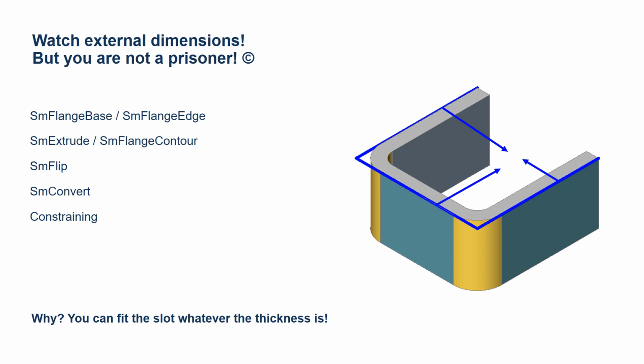And next, an evident thing is that sheet metal by default preserves the external dimensions of the part. For example, when you create the model from scratch or edit it, it is usually designed in such a way that it doesn't exceed the external hull, but expands inside. And the decision where to extrude each part is based only on analysis of the input geometry, and so far we don't interact with the rest of the parts in the assembly.